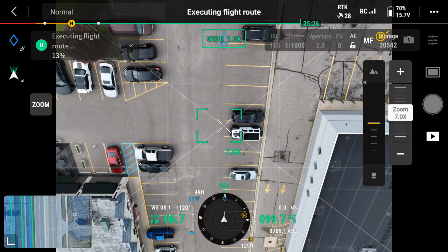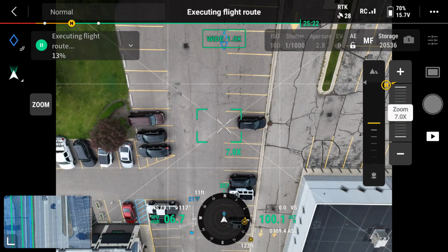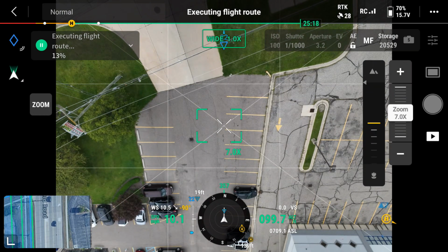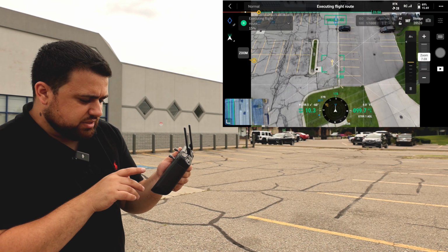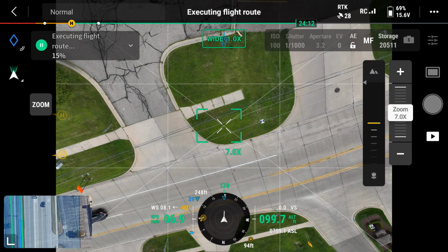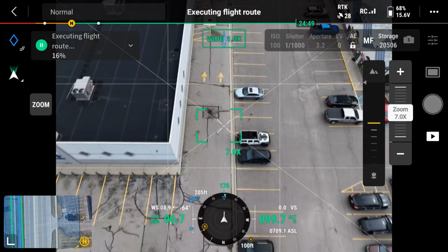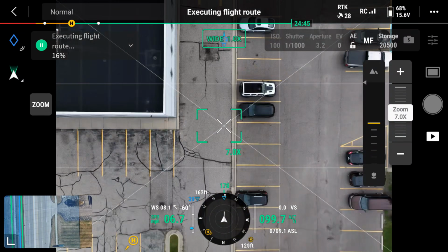You can see now with the oblique measurements, it is pitching the camera several times to 30 degrees. So it's taking the shot, and you can't obviously see it in the sky, but in the camera here, you can see how it's pitching back and forth. That's the oblique measurements. It's trying to take it at different angles, and it's sweeping back and forth the camera. And it's amazing how fast it's able to do that while flying at the speed that it's flying at.